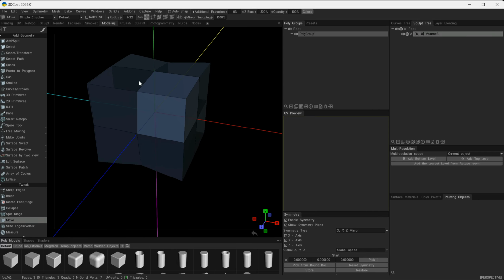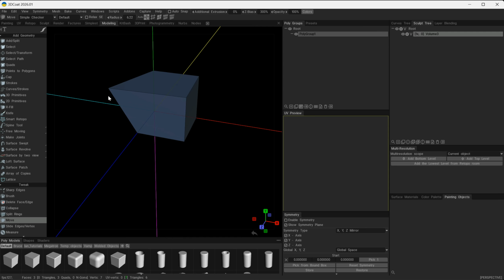So this is an important part to just keep in mind, because this does have an effect. And you can see that because I move this away, if I lower that, then it tears the mirror. So if you pull this point right the way over here and then forget about it, then you'll think, I've lost that point. It is there, it's just you've pulled it right the way over. And to show you what that looks like, if I turn off symmetry, you can see that's where you pulled the point to. It's just that the mirror was giving you a false impression as to where that point was.